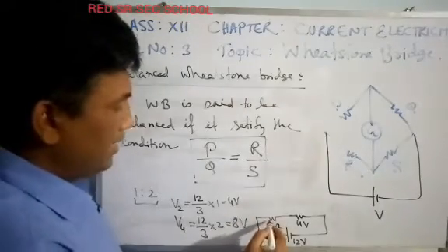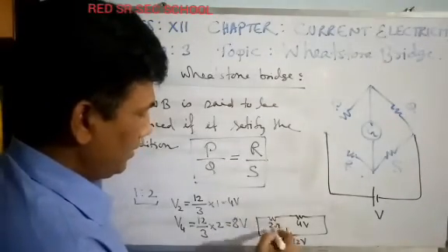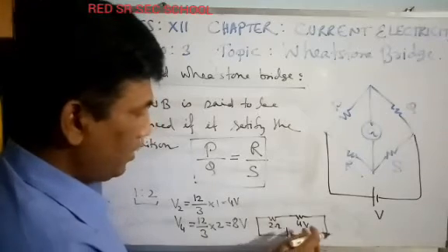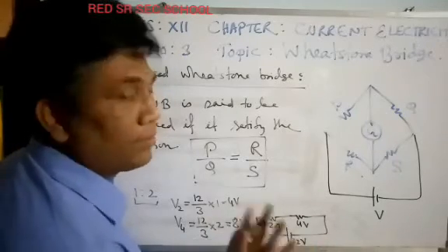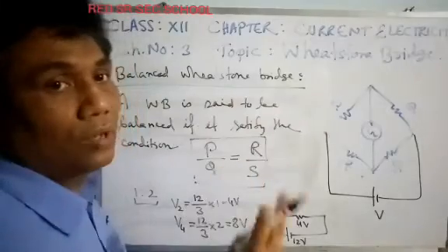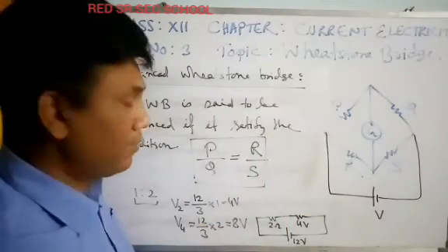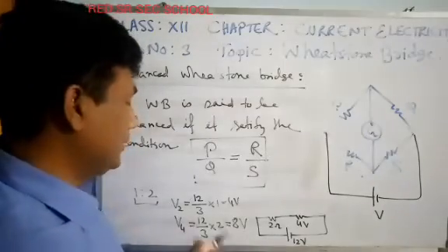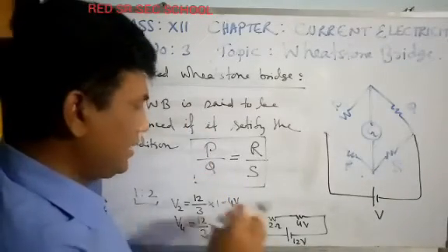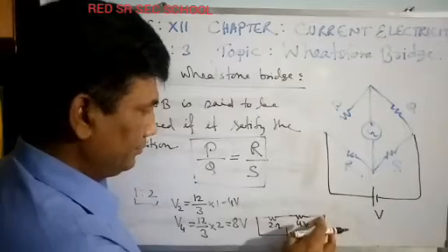And here I see the voltage drop is 4 volt, here I see 8 volt. Total 12 volt. Okay, Kirchhoff's second law is also valid now. Na? Total voltage supplied and voltage drop both must be the same. Good. Take another example. Say it is not connected here.